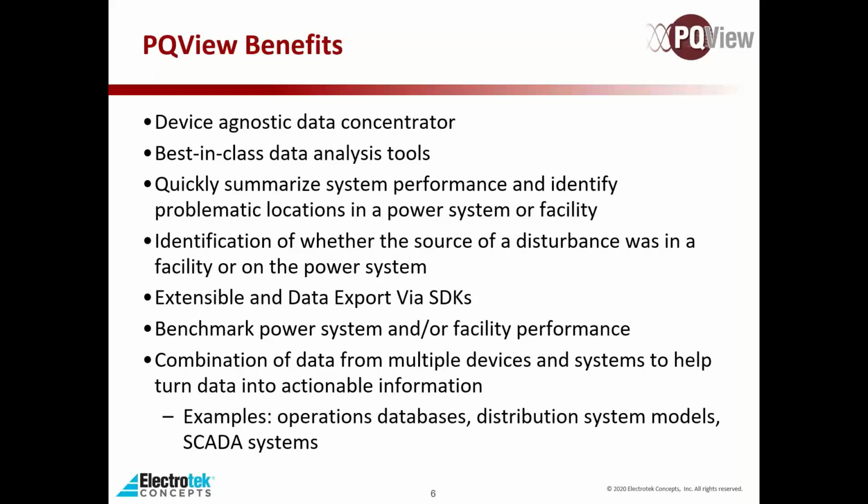You can plot where on the model that reactance to fault occurs. And then by looking at operations databases, you can narrow down which feeder it was based on which breakers tripped. And information from the SCADA systems can provide even more details and ways to pinpoint that down. So before, you just had a bunch of disparate sources of data. Now you have the fault location capability.